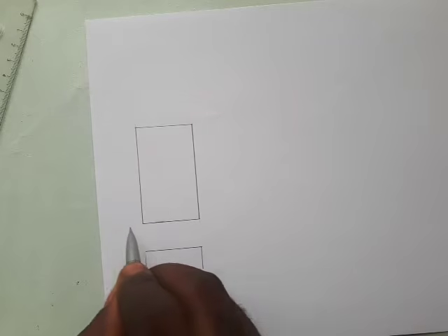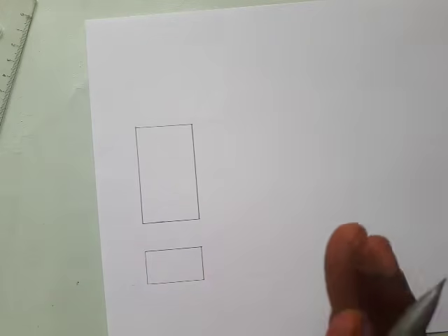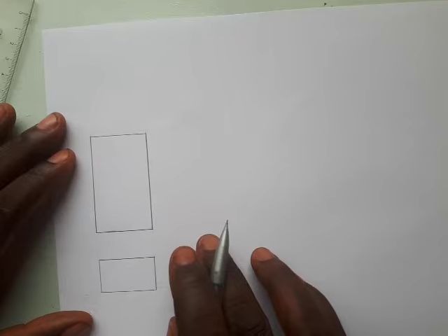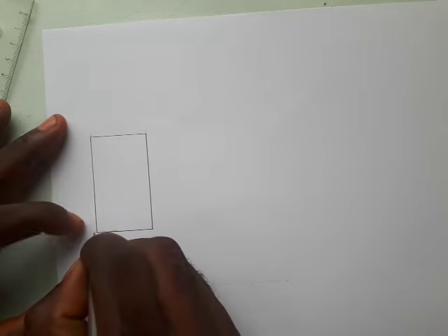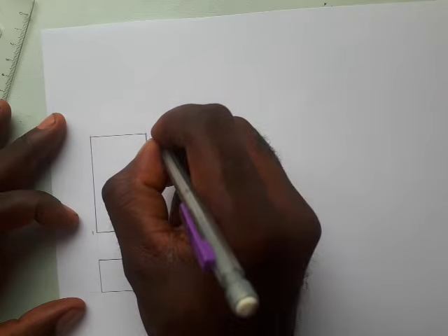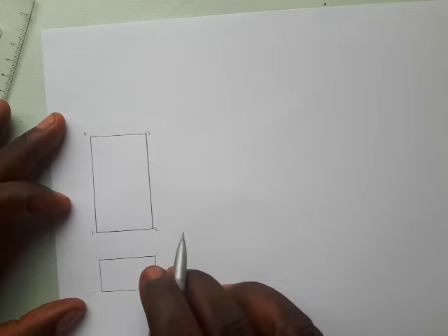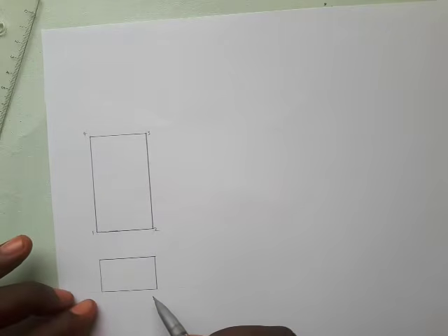So what do I mean by defining it? Now you can label the edges, give them a certain number. Do you understand? Give them a certain number, so it will help you in the process of drawing the auxiliary elevation or plan. So just follow me. All right? So what I'm going to do now is I'm going to call this 1. I'm going to call this 2. I'll call this 3 and 4. All right? Good. So I'm going to transfer same to the bottom.